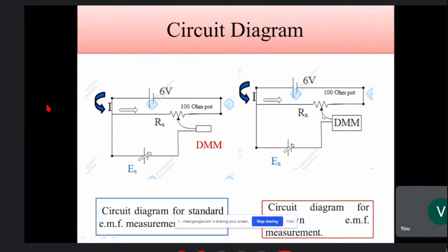Using that, you can find an unknown voltage. So this is the principle of a potentiometer. First, you have to understand the principle of potentiometer, how it balances, and the null condition, you have current only through this part of the circuit. So you know what is I. He is using I, though we are not using it, we are getting a cancellation from numerator and denominator, but this is 60 milliampere. So I hope this makes things clear.